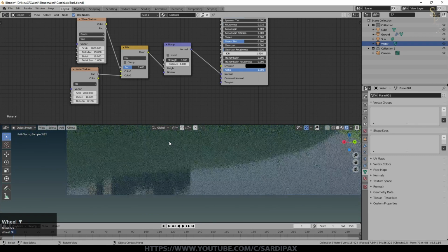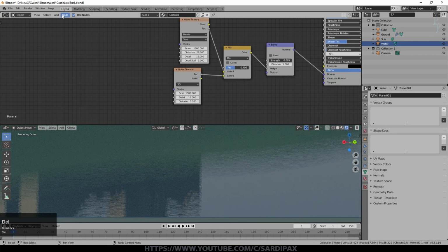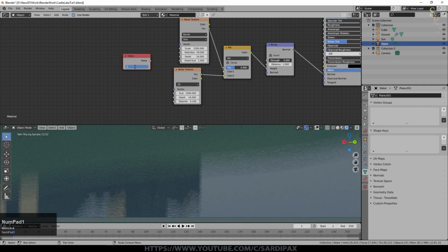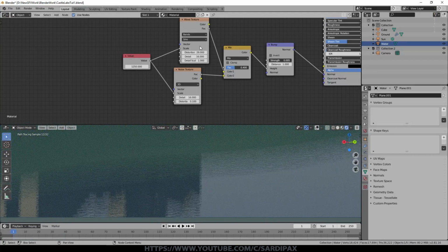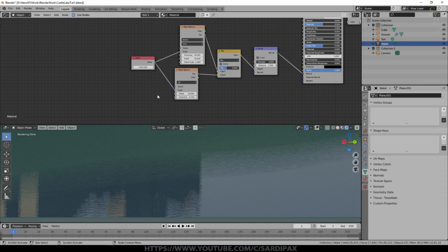Now, as I said, I think the scale of this is slightly smaller than the scale of my other one. So let's try 1500 for both of my objects here. And here's a little trick. If I am going to maintain these at the same level, I can actually add an input, which is a value. I'm going to set this now to 1250, and then just put that into each of those. If I wanted them to be a multiple of each other, for example, say I wanted this one to be twice that one, I could add a math node between those two that would multiply it by 2. So that now means I've only got to enter it into one place. Also useful, of course, if I'm going to convert this into a single node. Just a useful little tip.